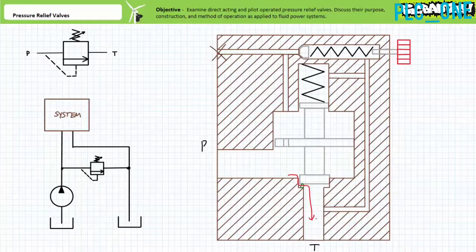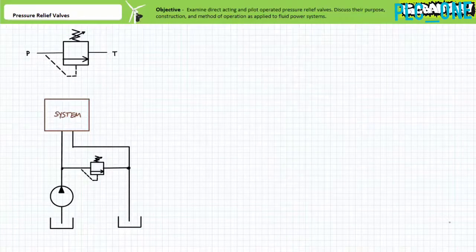Both these scenarios involving contamination may warrant the removal and repair or outright replacement of the faulty pressure relief valve. Both scenarios could have been prevented with a proper level of filtration and regular maintenance. This really wraps up the brief introduction of pressure relief valves I intended to accomplish in this lecture.